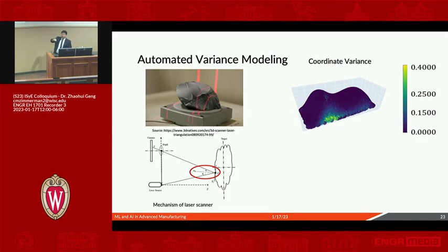The other one is regarding the height. If the height is very low, meaning it's closer to the scanning table, there are some reflections from the scanning table to the part that will interfere with the scanning laser, so the variance should be higher, right? So here we have an empirical study.